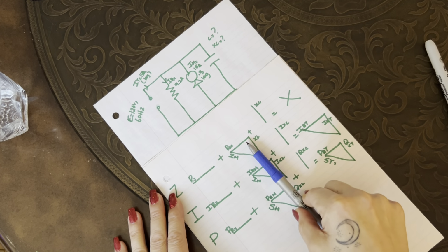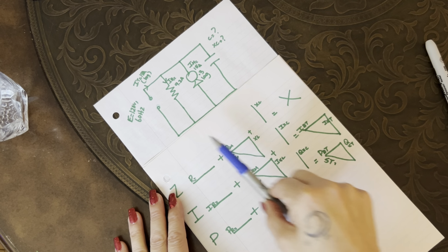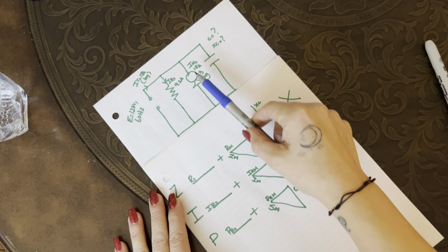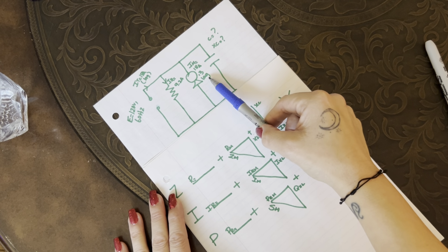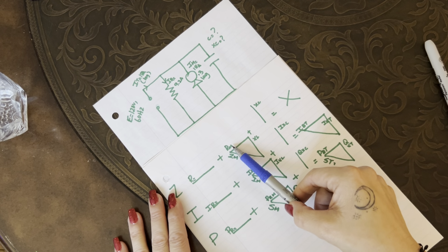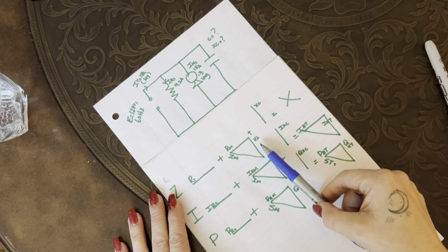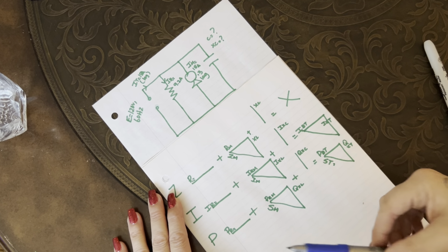The motor is flipped to what it would be in series because now I'm referencing from voltage as my constant, right? So there's a motor that has 18 amps of current flowing in it, 0.3 lag. So it isn't a pure inductor. That means it has a variable of resistance in it as well as inductive reactance. Therefore, it has its own impedance. The current triangle is going to be the same.